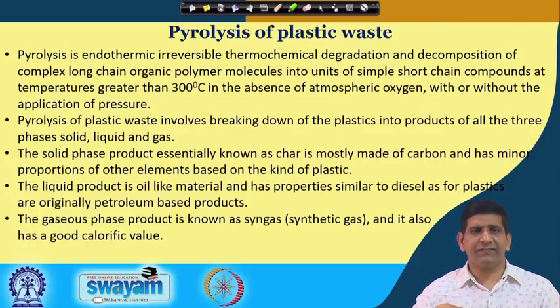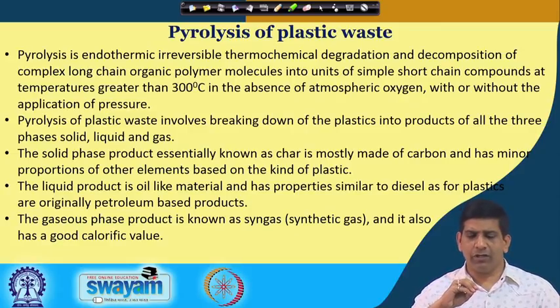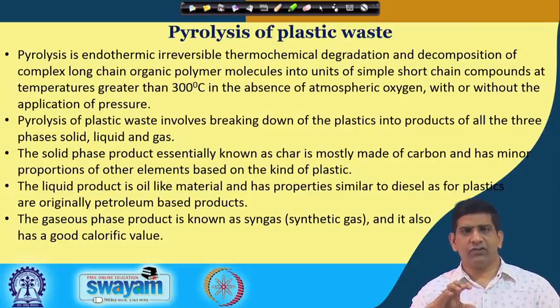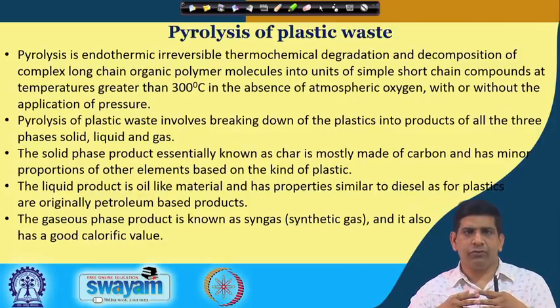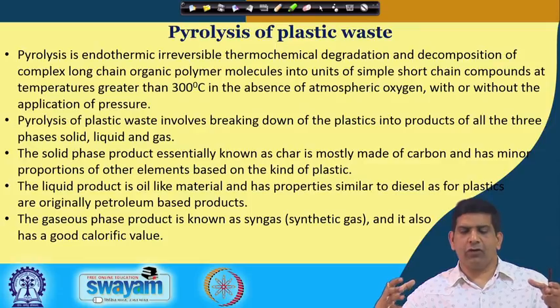So pyrolysis, what are you doing? It's a thermal or thermochemical process, we can say. It's endothermic, not isothermic. Endothermic means we have to supply energy, and it's irreversible: you cannot change it after it happens. So you are doing an endothermic, irreversible thermochemical degradation and decomposition of complex long chain organic polymer molecules, because that's what you have in plastic.